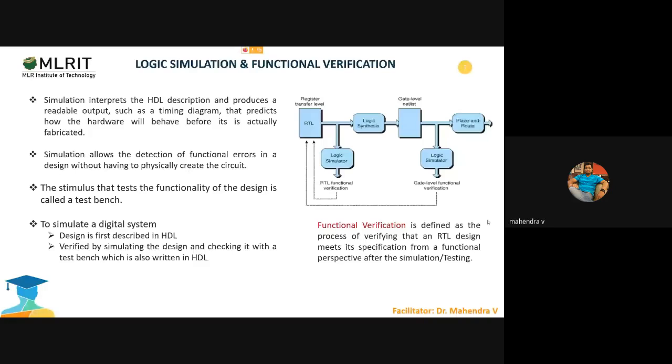That is how functional verification is defined: the process of verifying that the RTL design meets its specification from the functional perspective after the simulation testing. After the functional verification we go to the next step, logic synthesis, where the RTL code that is written and verified is converted into the gate level netlist.